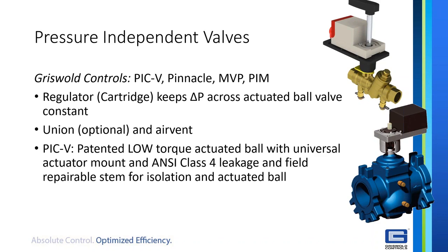And then we've got the MVP, which is shown on the bottom right, and then the PIM-V valve. And so they all have the same function where there's some pressure regulator maintaining a constant pressure differential across the actuated portion of the product.